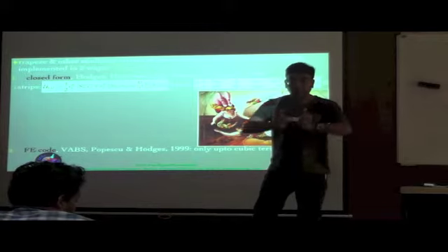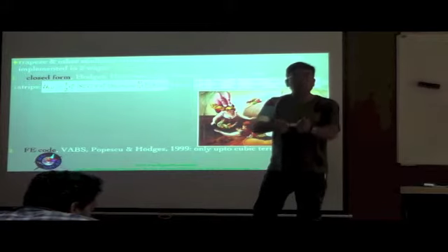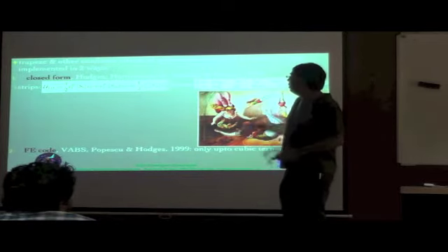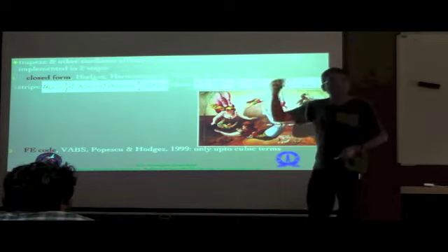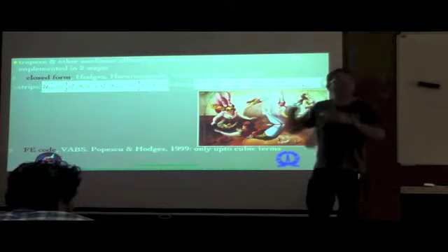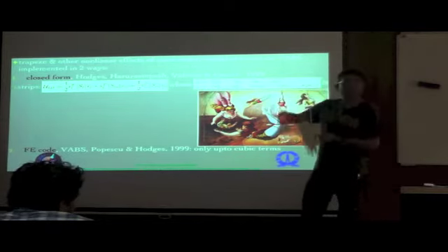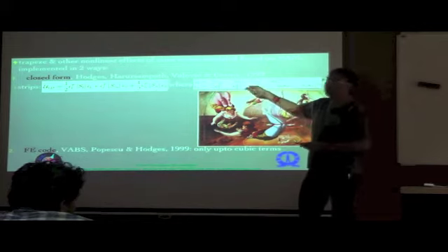Now kappa 2 can be much larger compared to kappa 3 because it is much less stiff in bending in this particular direction, and therefore the contribution of kappa 3 squared terms will be much higher order compared to the contribution of kappa 2 squared, and that's how automatically the variational asymptotic method leaves out that term.